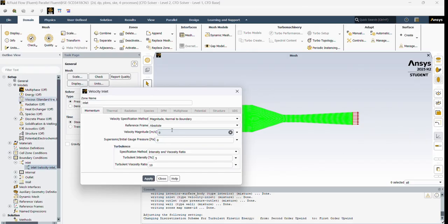So we had to calculate the velocity of the inlet. We know that the area of the inlet times velocity of the inlet is equal to the area of the test section times velocity of the test section. We use the height for the area values, as the base of both would be the same.